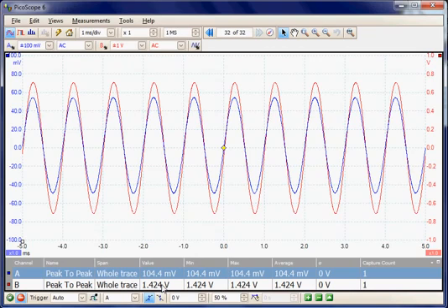So on this particular amplifier gain setting, the gain is A divided by B, so the gain is ×14. But it's very easy, you see, to monitor the input and output levels. This is called the overlay display. We're overlaying channels A and B on one panel, but they can be displayed in separate panels.